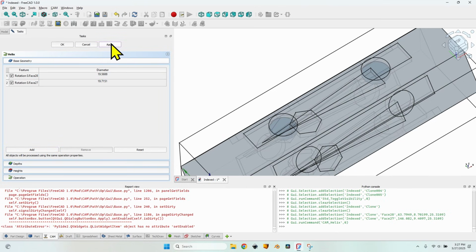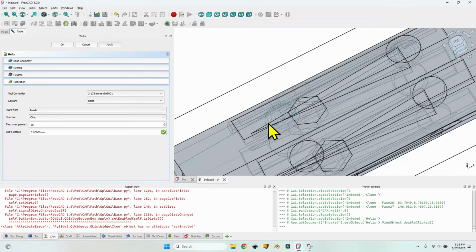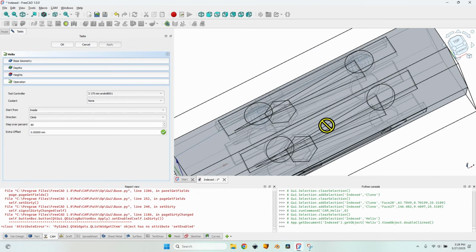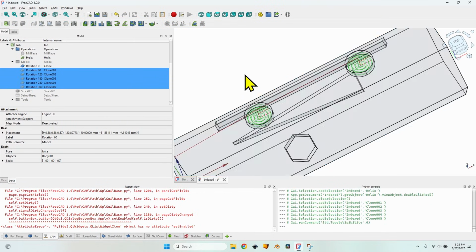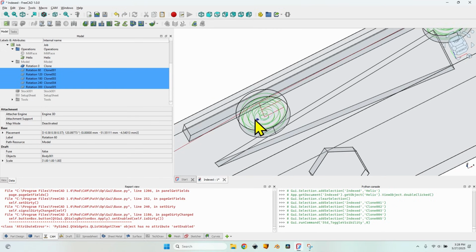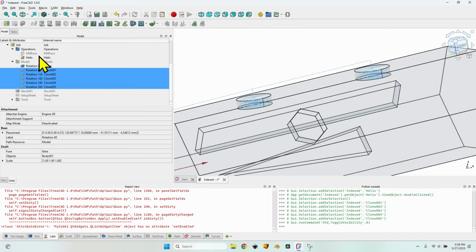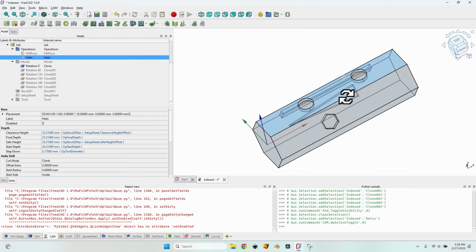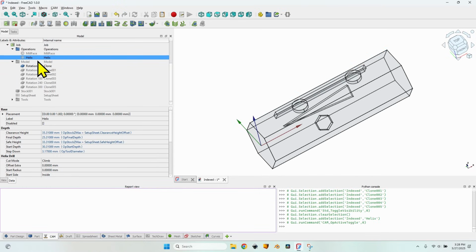Click on the apply button, and now you can sort of see some Gcode here, because again FreeCAD turned the visibility for all the objects in the job, which is kind of annoying, but that's the way it works. If I hide them, you can now see the toolpath for the helix, which is exactly as it should be. I will also disable this operation for now because I want to be able to see everything that I need to set up.